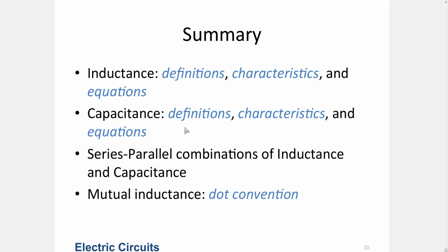Depending on the direction of the coils on the transformer core, we have to take these directions into account when writing down equations. If the dots are the same in parallel on both sides, then the voltage polarities will be the same. If they are opposing each other, the voltage polarities will also be opposing. We have learned those things.